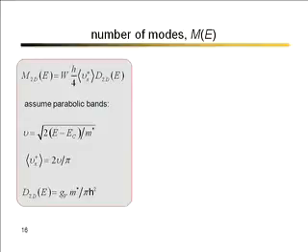Now, commonly in semiconductor textbooks, when you compute densities of states, because you know that the density of states in 2D is proportional to the area, what you usually see quoted is the density of states per unit area, per unit energy. So that's what I'm writing here. The 2D density of states per unit area. And G sub V is a valley degeneracy.